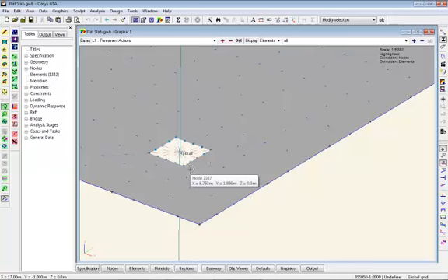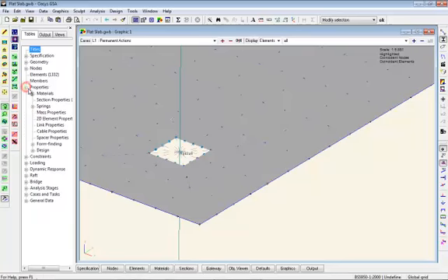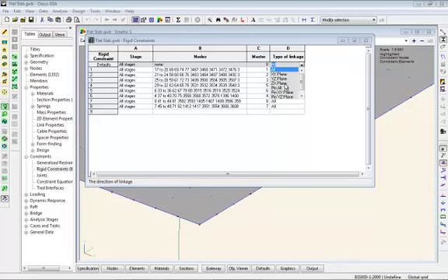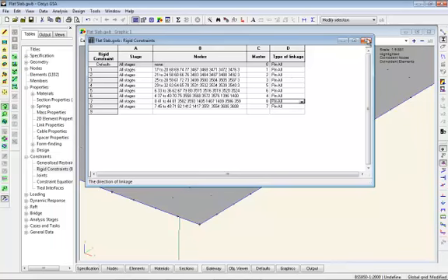I've put a link into that point, and so you don't get the very high peak moments over the column center line, because the columns in the analysis model are one-dimensional. They're like a pin, but in reality they do have sizes. Now let me just check that constraint. Okay, they're currently all. I'm just going to change those to pin all, so I don't get the moment transfer between the individual nodes themselves.